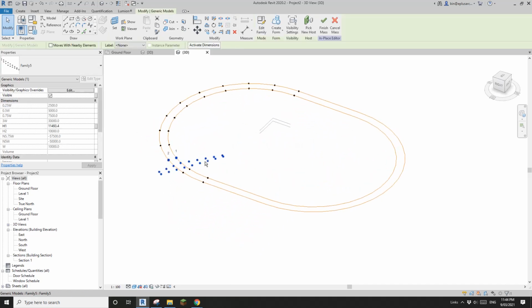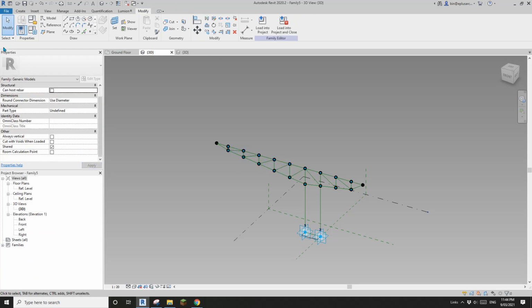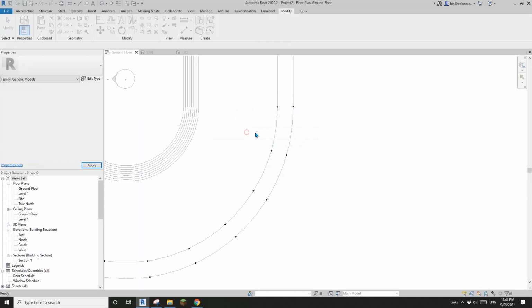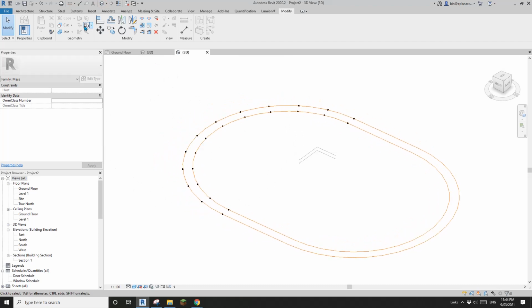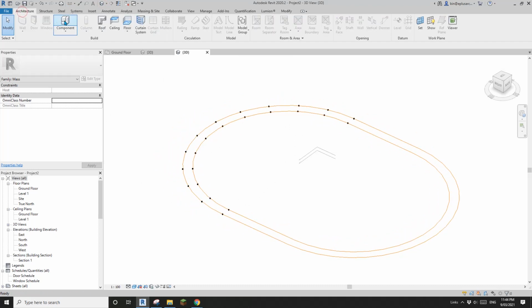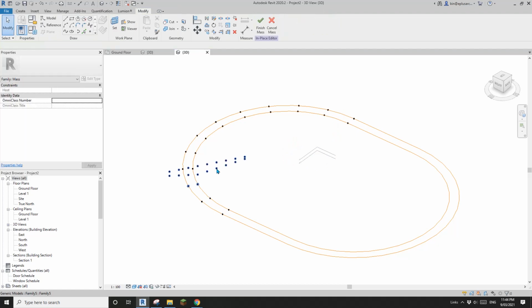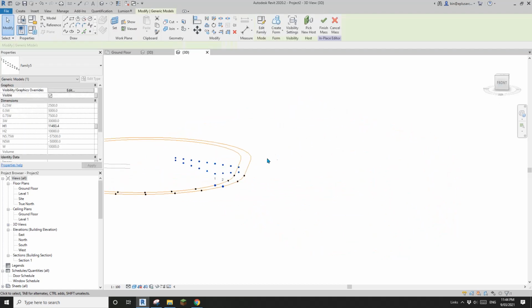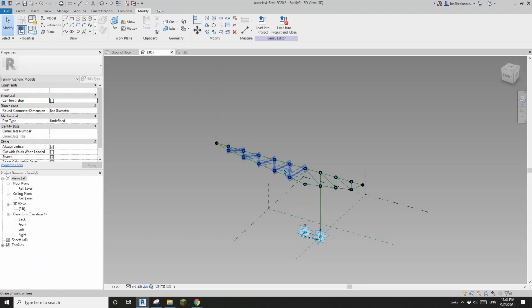looks like okay, something's not right. So let's go back to this family. Here under properties, check this always vertical. Okay, and then load this back into here, and then let's go to 3D view. It disappears. That's fine. If I create another one anywhere and escape, you will see it's back. And also you won't see anything. This is because they are all reference lines.